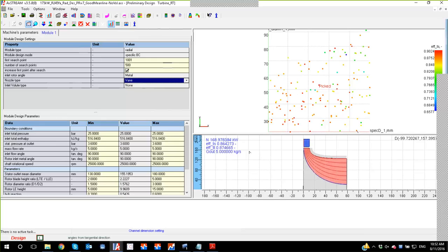Here, one thing that we could do from here would be, okay, I have 7 minutes left. We could look at different rotational speeds. So instead of 25,000, I could bring it down to 1,500, and then see how that's going to be affecting the performance of the machine that I can design here.